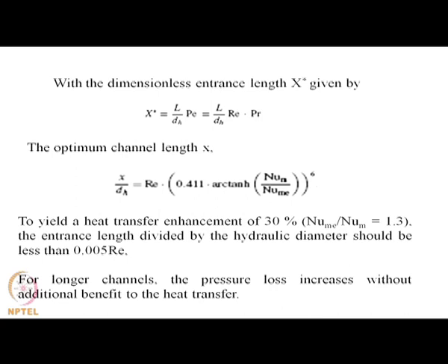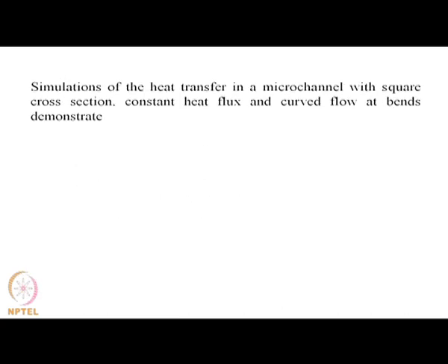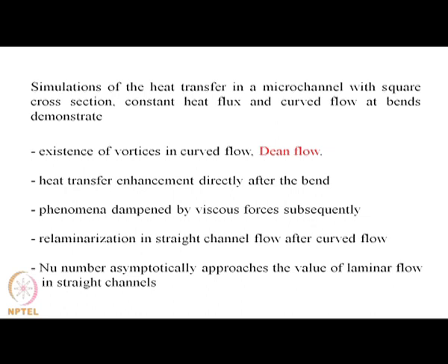So, if you know your Reynolds number, if you know the value of dH, then you know what would be the entrance length to obtain a certain percentage of heat transfer enhancement. But there is obviously a limit to this. If you use a longer channel, then the pressure loss increases without any additional benefit to heat transfer. So, simulation of heat transfer in a microchannel